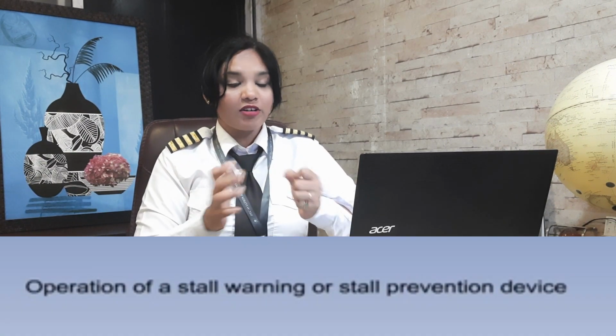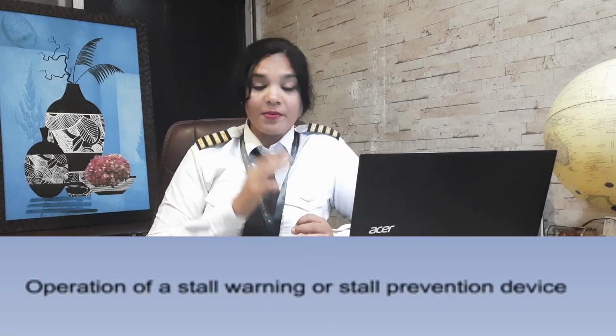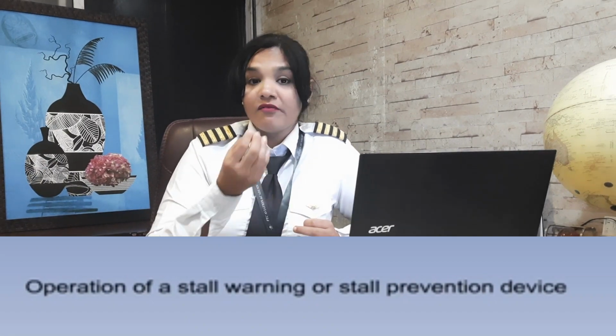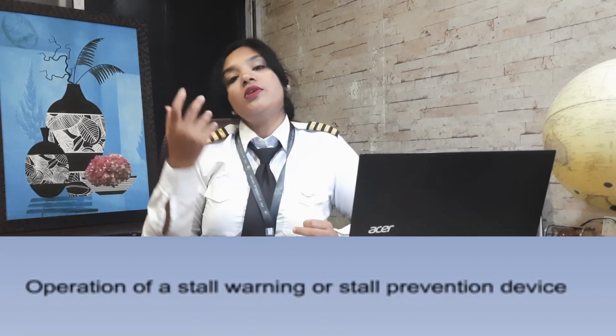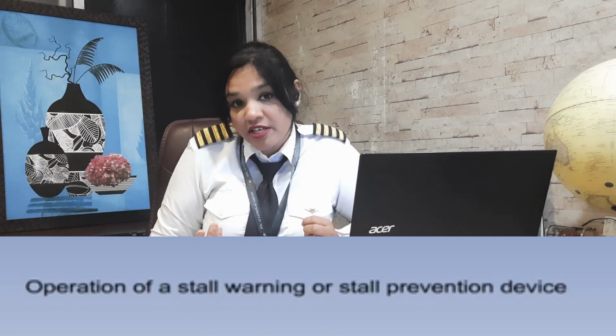This is called aerodynamic buffeting. And lastly, operation of a stall warning or stall prevention device. Each aircraft will have a stall warning device or stall prevention device, which will alert the pilot that you're about to stall. In some more sophisticated aircraft, it will actually prevent stall. These are some of the symptoms of an incipient stall.